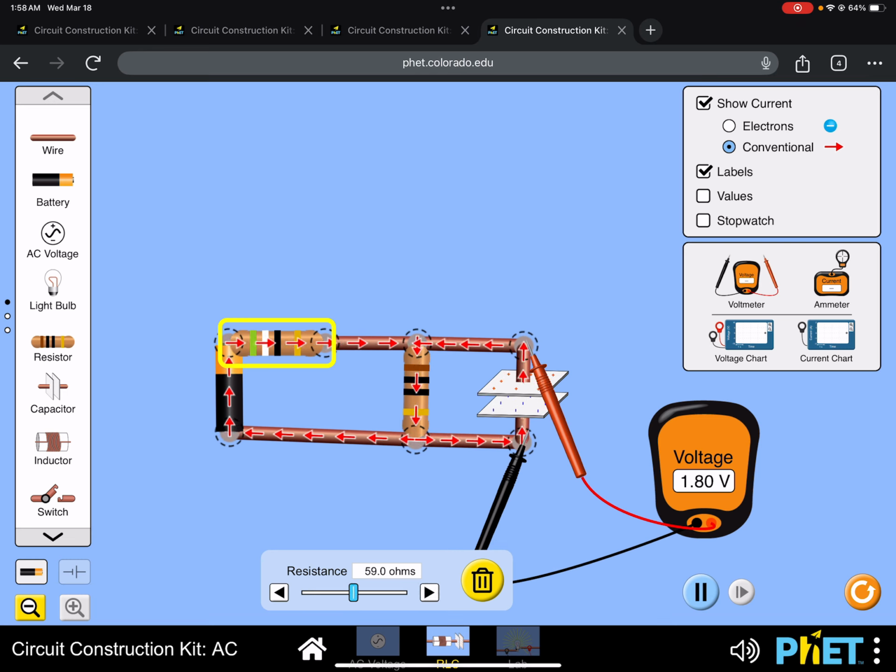So here we see that the voltage is going to be decreasing. It was previously at 5 volts. And look how little charge is on there. Let me increase the resistance even more. All right, and now my voltage drop across my capacitor went all the way from 5 down to like 0.78. And there was barely any charge on it.